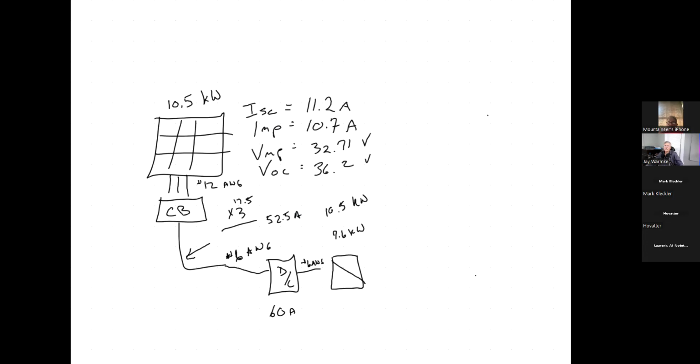Okay, so I'm going with my 7.6 kW. From here, I go to an AC disconnect. The AC disconnect has to be located within 10 feet of my electric meter outside, be externally operable, and be well marked. All right, what size wire do I need here?